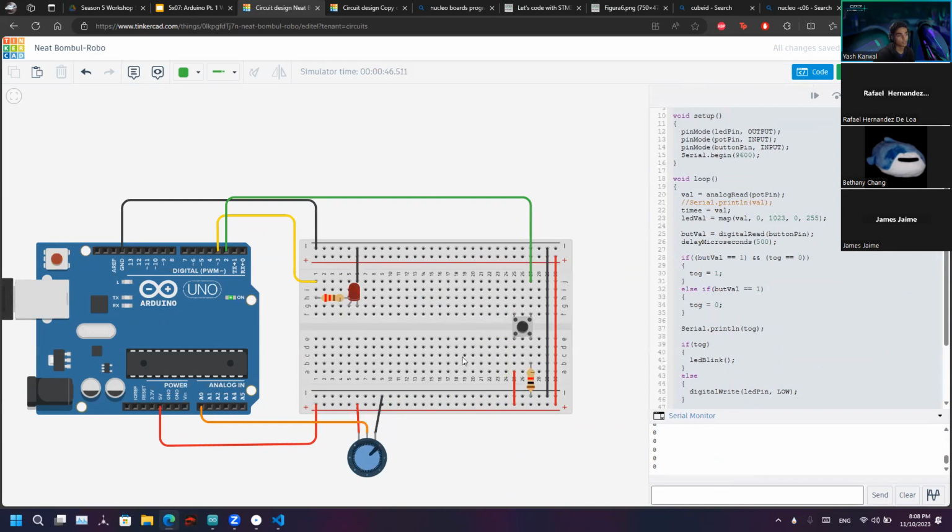Yeah. Well, so when I hold it or click it, I see zeros, but it doesn't toggle. Maybe it's toggling too fast. Yeah, or it's just not reading it fast enough, or it reads too many of them. That's the problem with buttons in general, because even in real life, when you press it there's a certain bounce to it where it might toggle your thing twice or something else.